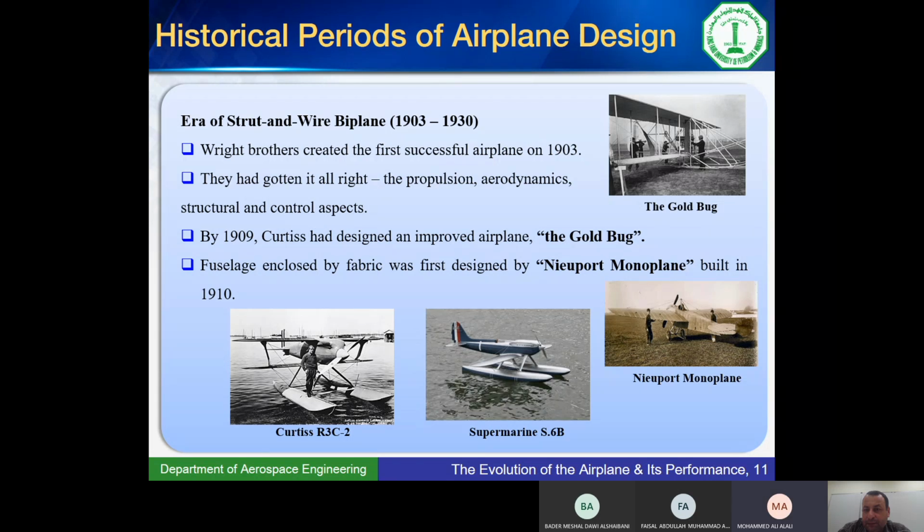Maybe it will have a lot of torque that will cause the wing to bend. Yeah, that's close to correct. Do you call it torque or do you call it bending moment? It has a lot of bending, right? The lift is going to bend the wing upward. Because it's a very long wing, it will tend to bend upward. The shorter the wing, the less the bending upwards.